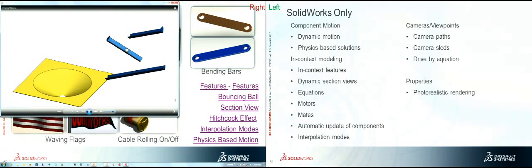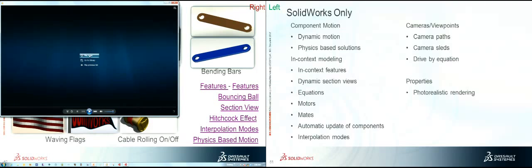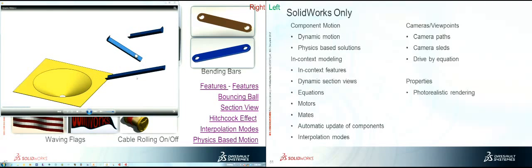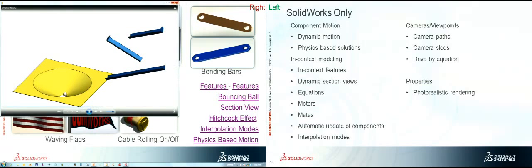And finally this one. This would be a little hard to do with key points. But we're using gravity, we're using contact, and this was done in Basic Motion because you can see one thing that doesn't happen. You notice the ball never bounces. It always hits the surface. That's one way you can tell it was Basic Motion.